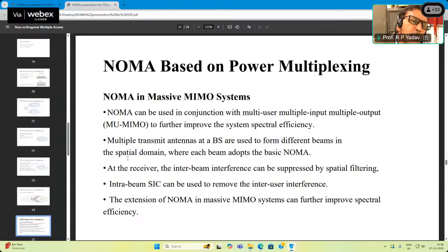How do we do the frequency planning? You have the cell, and the same frequency can be used only after a certain distance, in a cluster pattern. Here, you can use the same frequency if you can generate a beam that doesn't interfere with the other user. The same frequency can serve both of them. Maybe one user is on the seventh floor and another on the ground floor. If the beam is sharp enough, they don't interfere, and that obviously will increase the capacity of the system.